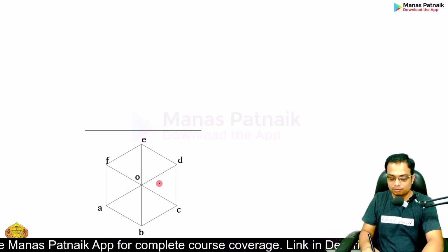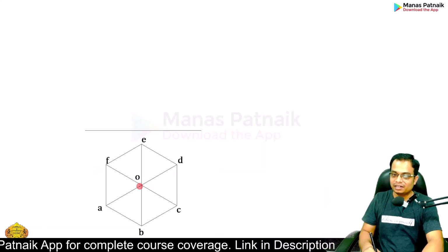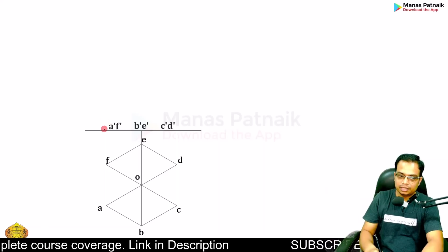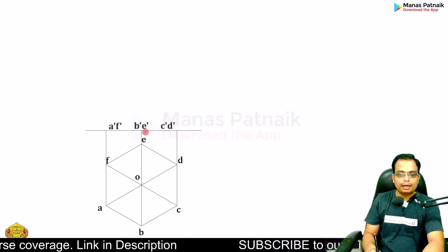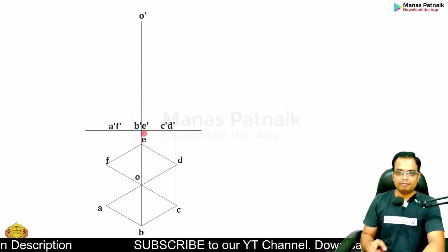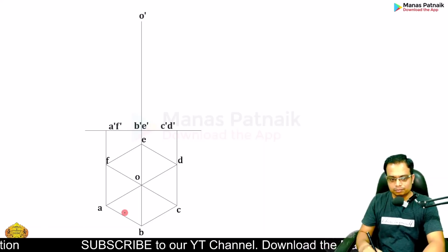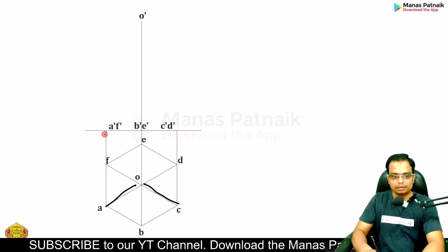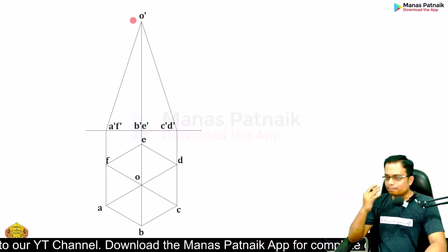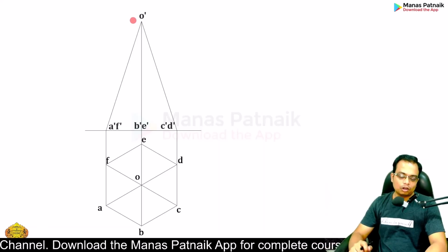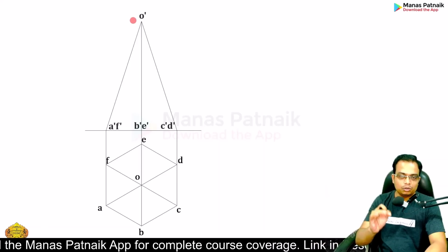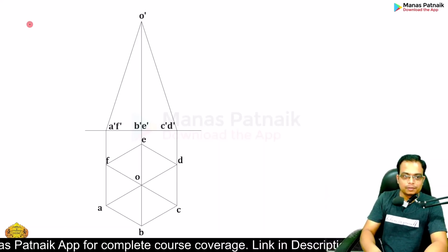By the way, these are the slant edges first of all. Okay, meeting at the center, and then draw the projectors. These are the points of the base, and then the axis length is 80. Okay, I'll be doing the dimensions at the end, don't worry. And then join. Done. Now you just need to make the development. Please remember, whenever you solve a problem on development, you have got to use or make use of true length. There is a check.